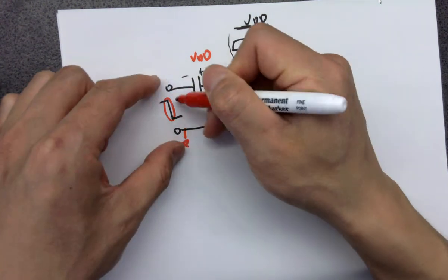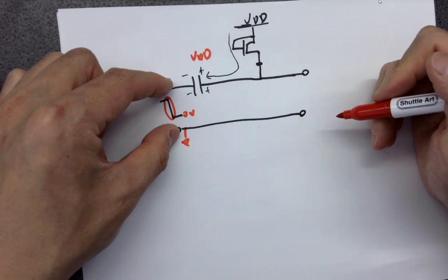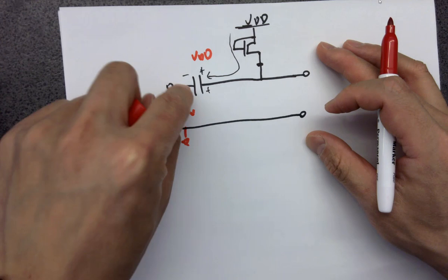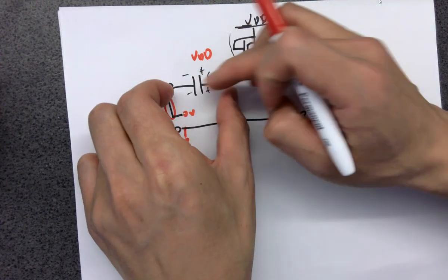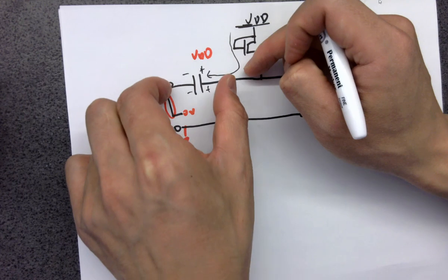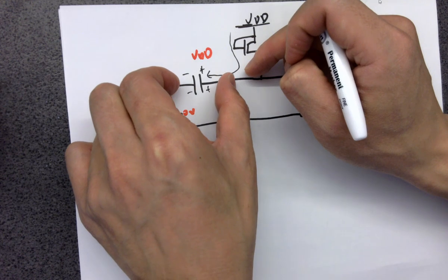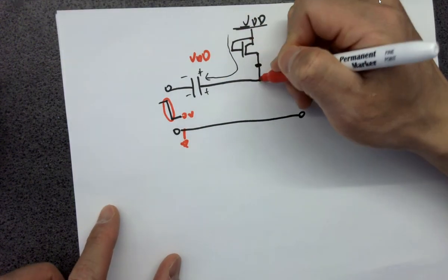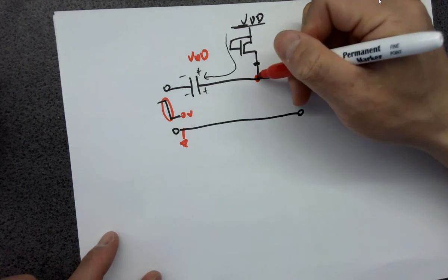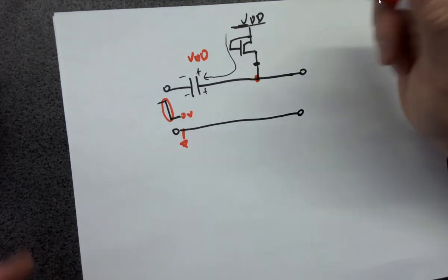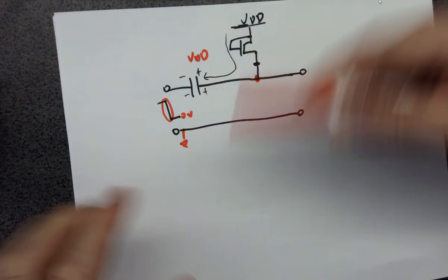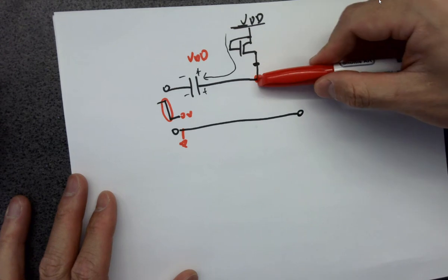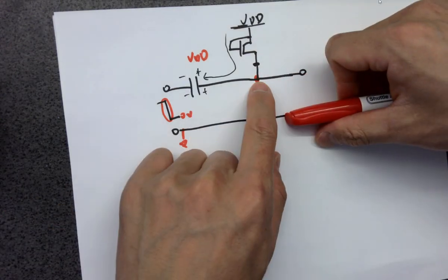And whenever the voltage here becomes 0 volts, there's no difference, which means here will be 0 volts as well, so it's dumping VDD to this cap. Ground on the other side, and eventually it's going to form a VDD over here. Ideally. However, what is the real voltage at this point? Because the NMOS is not good at passing ones, so you are not able to get the entire VDD to this point.